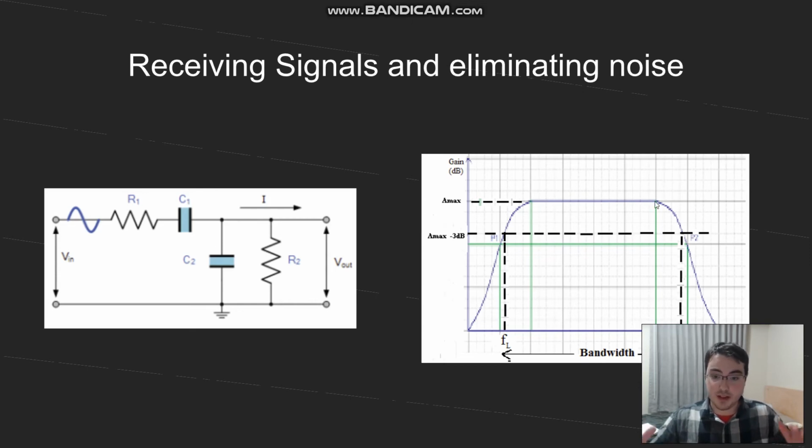And you design it to be a tight bandpass, so it quickly cuts out the signals from the other frequencies. What that allows us to do is pick out a signal from a crowd of other signals. So this has been a brief description of how a radio system transmits a signal from a cell phone and how you can possibly receive one from your cell phone.